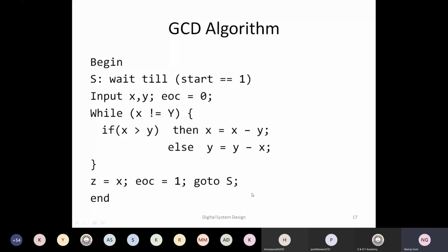in the image processing application, which we have seen in our previous part of the session, the steps could be different based on the number of multipliers and the number of adders. Although the requirement says there are 9 multiplications required to design one pixel processor, if the number of multipliers given is not 9 but 5 or 6, then the hardware would be slightly different, but it can still be done.